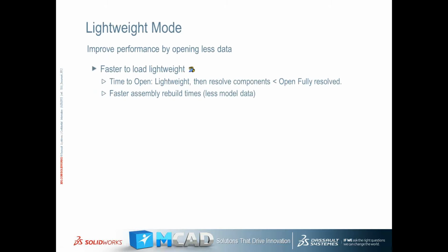Lightweight mode. Okay, everyone should be using lightweight mode. Essentially, the time that it takes to open and then resolve from lightweight is actually less time than to open a fully resolved assembly. And I've done a number of tests on this, and almost every single time the amount of time is less to open it lightweight first, then fully resolve the components if I really wanted to do that. Okay.